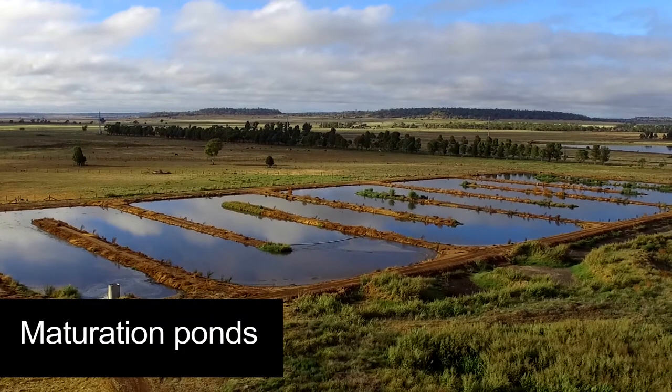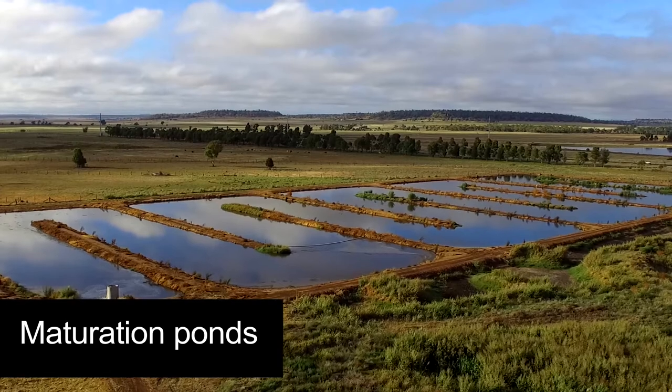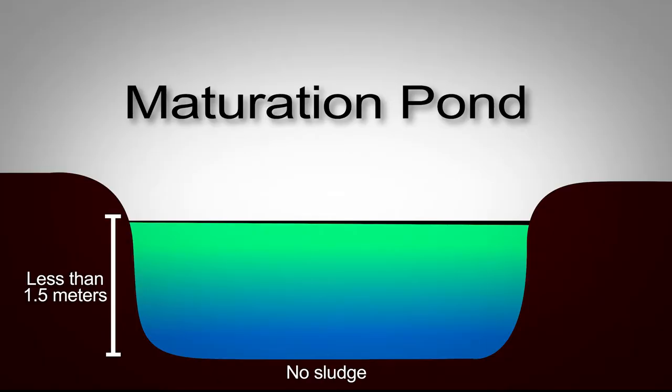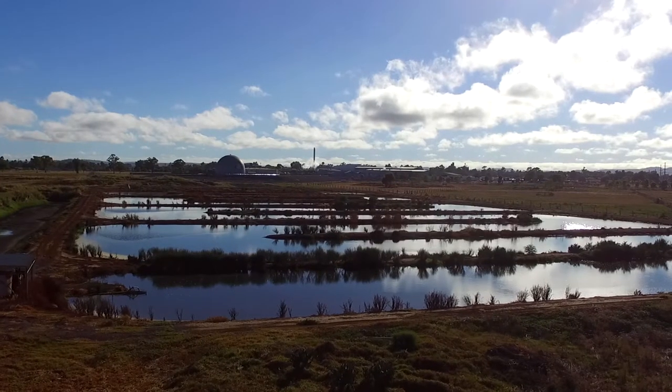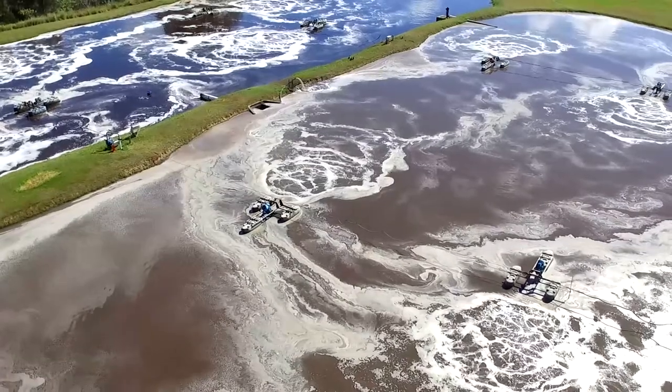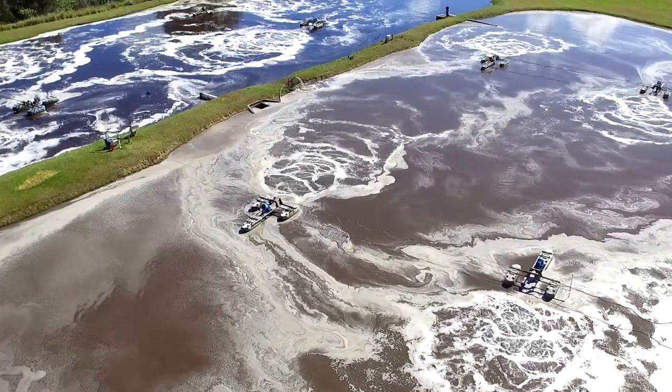Maturation ponds are shallow ponds, often less than 1.5 metres in depth, that are designed mainly to achieve disinfection by reducing pathogenic microorganisms as well as reducing BOD to low levels. To do this effectively, they have treatment systems upstream, such as facultative or aerated ponds, which reduce the incoming BOD load to very low levels.